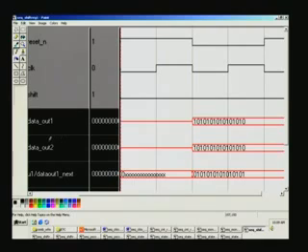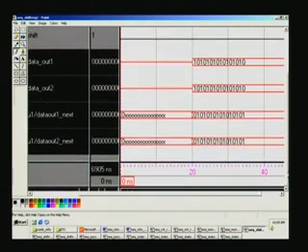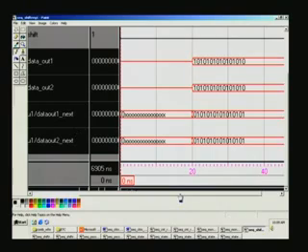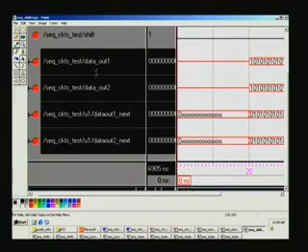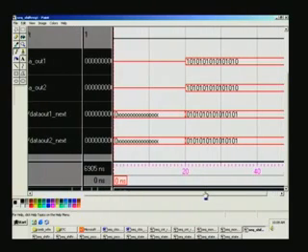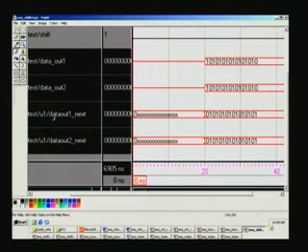And so also data out 2, which is the alternative approach for the shift. Once again a corresponding next will be there, pre-shifting. So it's enough if you have a look at the data out. Actually we'll just have a look at one data out next. If you see, it will always pre-shift. Because it is a right shift by 1 bit, 1010 has become 0101 here because it was right shifted. So this will be assigned to this only with the following clock edge.